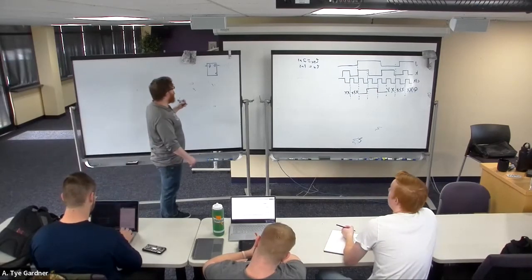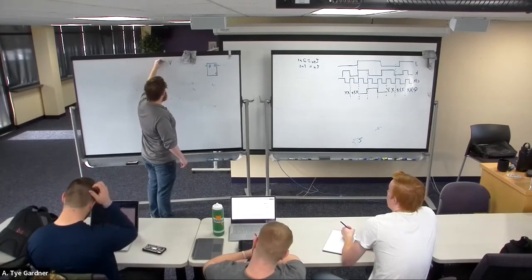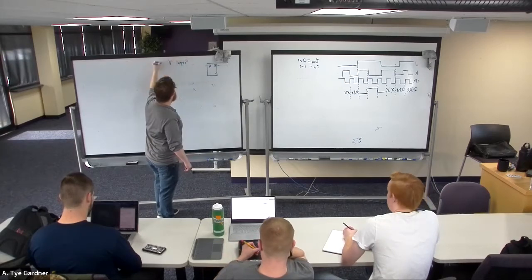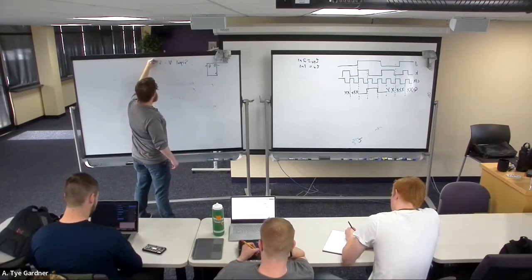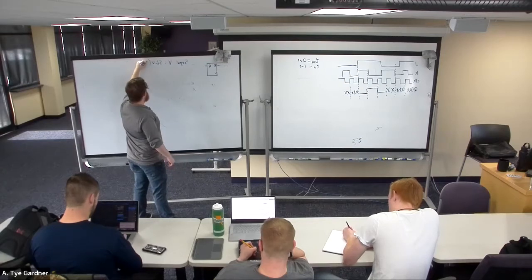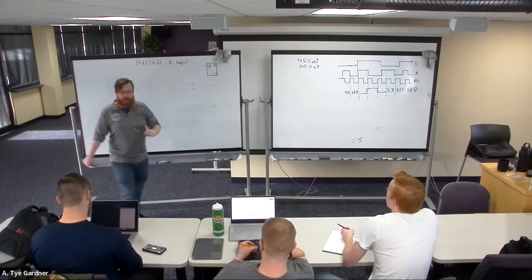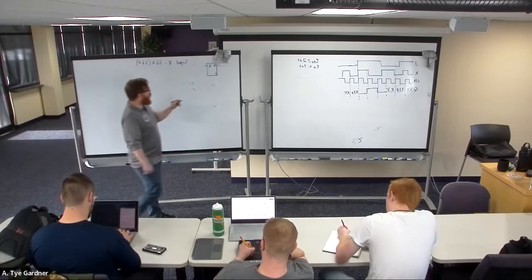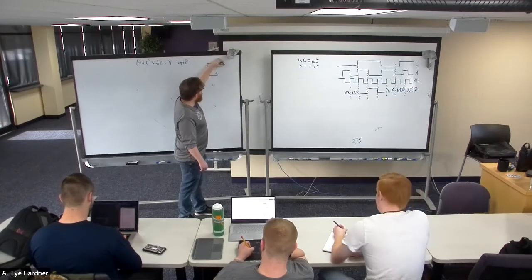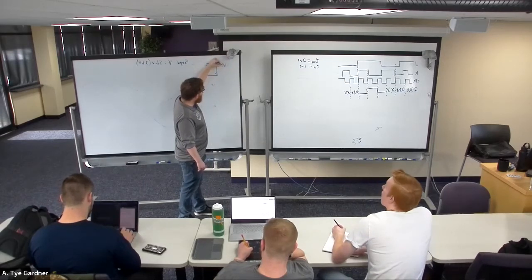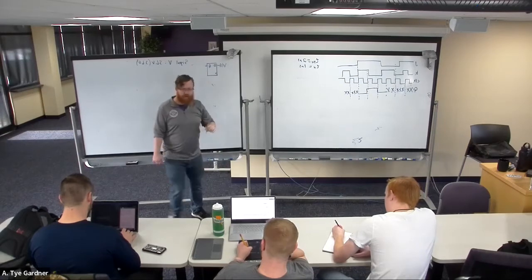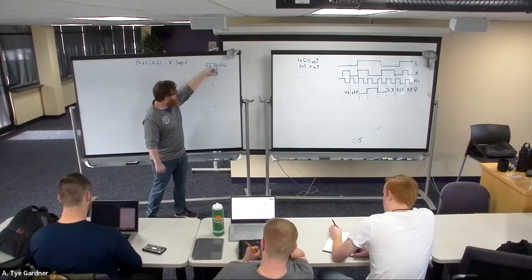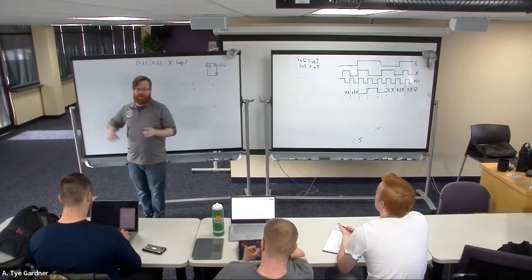If I had a vector V, and I declared it as a signal V is a standard logic vector of 3 down to 0, this is a 4-bit vector, right? That means that this can remember for me V at 0. So I put V in here. There's a rising edge of the clock or fall. If I want this to be falling edge like we just did, there's a bubble. Now it's a falling edge trigger device.